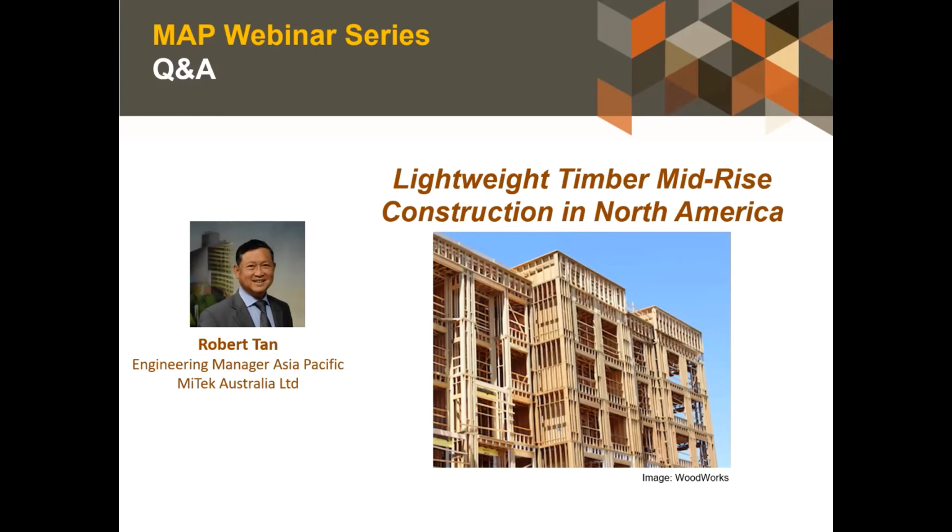Another question here, do they have particularly high lateral earthquake loads? Where we visited, yes, we did Los Angeles, as you can imagine, and up towards Washington and Minnesota, Minneapolis. They're all very high earthquake regions, which is why these rods are very cleverly designed. Although you normally expect to see a larger diameter rod on the ground level tapering up to a smaller rod at the upper levels, it is not necessarily the case. For the dynamics, it can actually be reversed as well, depending on how much movement they want to restrict at different levels. And they sometimes even use high tensile rods for that purpose.